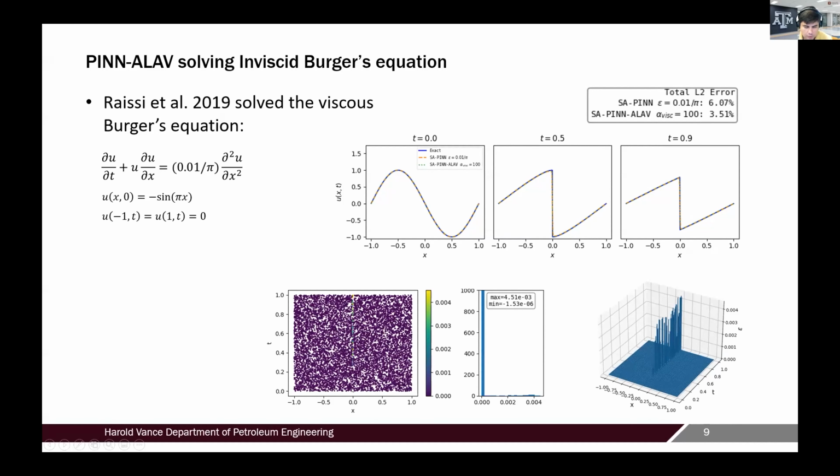And on time 0, that is this bottom part here, there is no need for artificial viscosity because there is no shock front. Okay, so these values start to increase only when we see the shock front happening. And just to make a better plot, I have this 3D plot here on the bottom right, where you can see the values of the artificial viscosity spiking only on the area where the shock is happening.